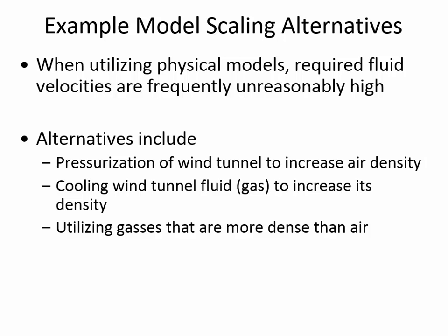One of the other advantages that we have when we're doing model simulations is that it gives us the flexibility to use different fluids besides just air. Even if what we're trying to do is understand, for example, the flow of air over a wing, we could switch to water as a fluid instead of air if that meant that we had different velocities that are more favorable for the pumps we're trying to use. Or vice versa. If you're trying to understand the scour on a submarine, submarines can experience cavitation on the propellers that they have on the end.